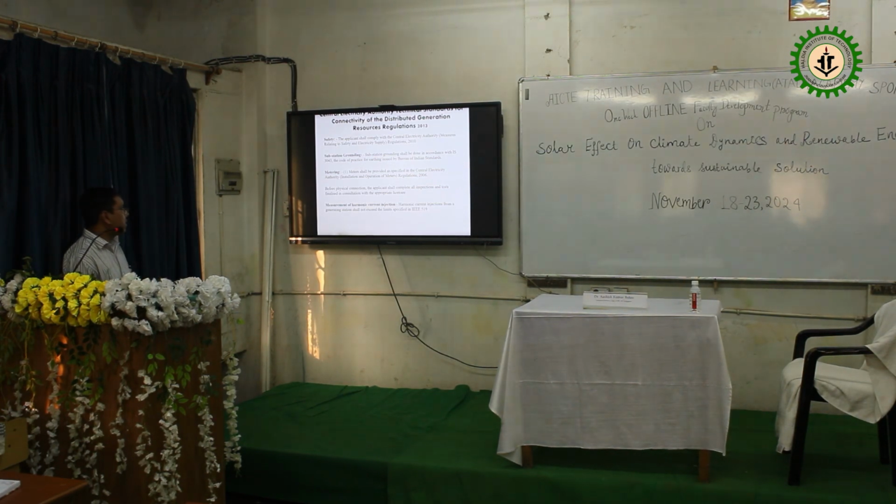Again, the Central Electricity Regulatory Commission or authority has regulations, as per 2013, that the system should be safe. Substation grounding is a must, as well as metering and the measurement of harmonic injections. Solar or similar sources involve inverter devices, so there is a chance of injecting harmonics into the grid. It should not be more than the permissible limit, as per the IEEE 519 guideline.